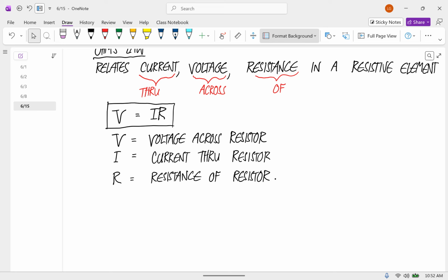But there are some devices in those cabinets that will require more voltage than one battery will provide, but not much current. And so then we'll just wire up 2 batteries in series, and it'll meet that voltage requirement. And since the current requirement is low, it'll be fine.